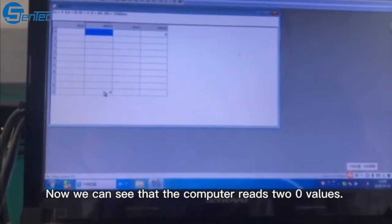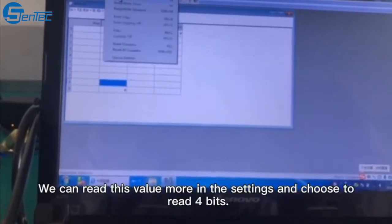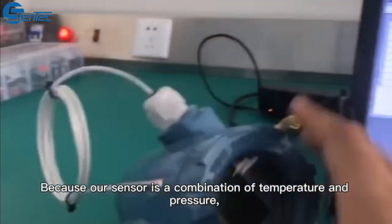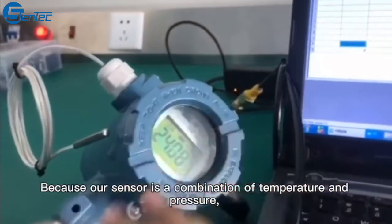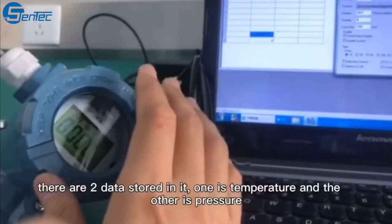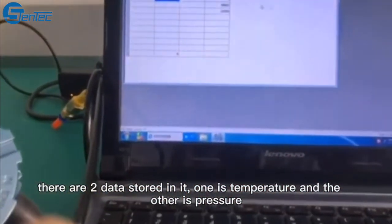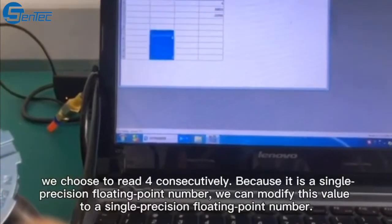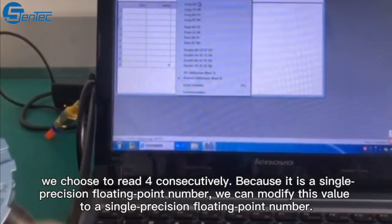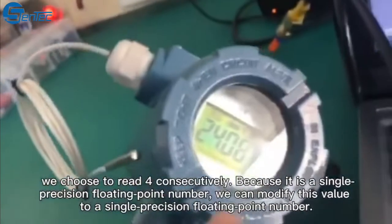Now we can see that the computer reads 0 values. We can read more values in the settings and choose to read 4. Because our sensor is a combination of temperature and pressure, there are 2 data stored in it. One is temperature and the other is pressure. We choose to read 4 consecutively because they are single precision floating point numbers. We can modify this value to a single precision floating point number.